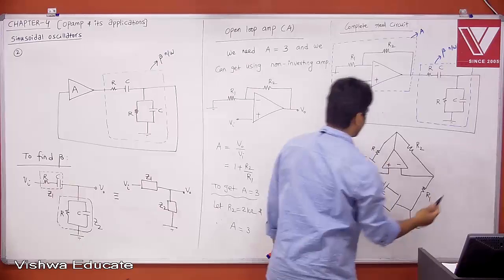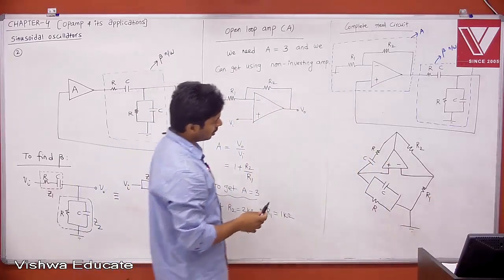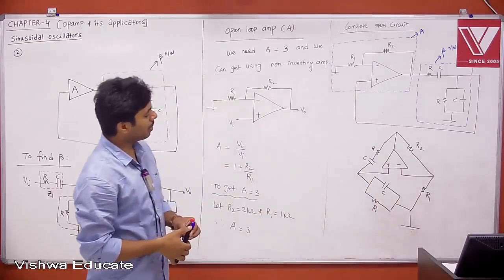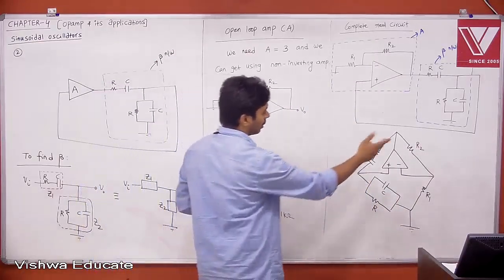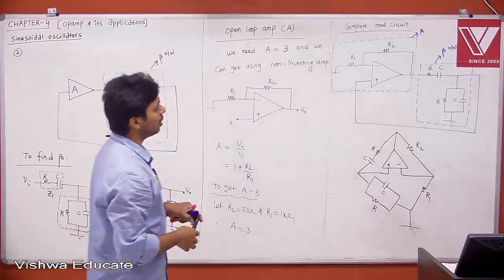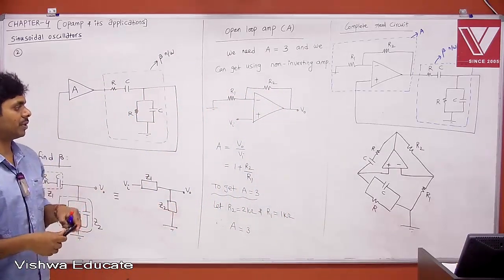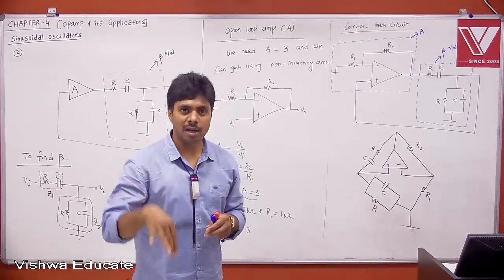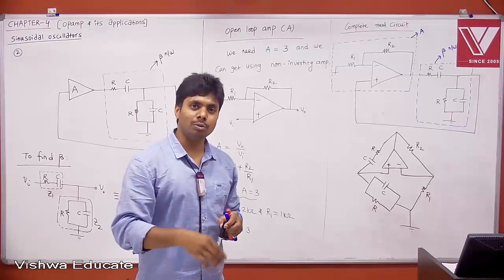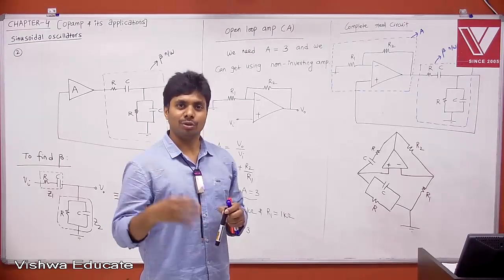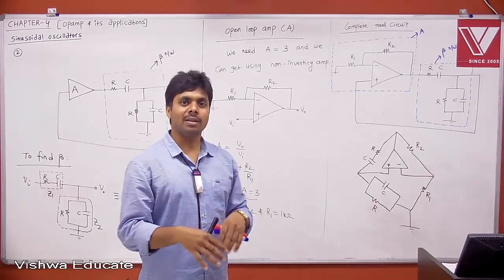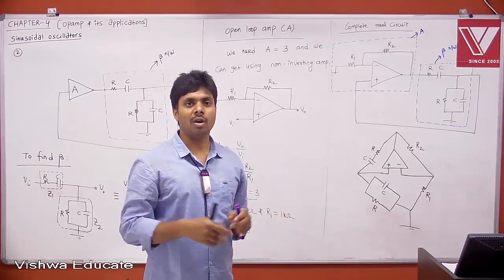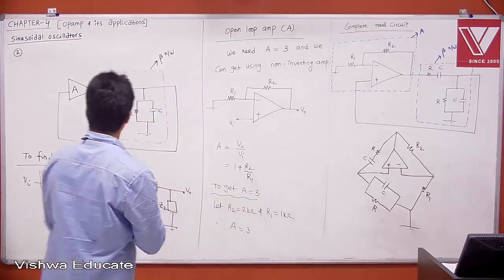Therefore, can I write like this? Right? This is a kind of bridge. Op-amp is in between, and R1, R2, series RC, parallel RC and then ground. Therefore, you can write the same circuit like this also. But if I give you the circuit like this, will you understand? Because we know what is Barkhausen criteria and we know what is total loop phase shift. You know what is beta network. You know what is open loop amplifier. And we combine, we are writing here and there, but it looks like a bridge, 4 branches, and in between the op-amp. Therefore, it is Wien bridge oscillator.